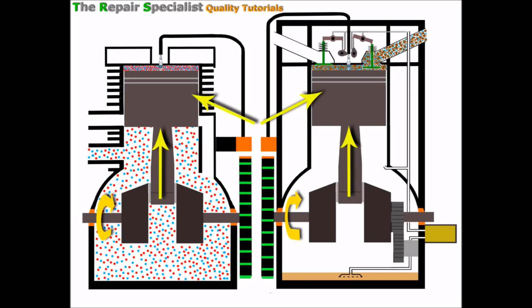Of course, now the pistons are in this position, those magnets on the flywheels are going to instantaneously pass the coil packs, generating and transferring the electrical energy, which again of course travels up each of the HT leads to the spark plugs. That again stimulates each spark plug to fire, and there's still a spark here on the four-stroke, even though we're at the end of the exhaust stroke, and there doesn't really need to be because it's not a power stroke. It still sparks because that magnet that passes the coil pack does so every 360 degrees, and that generates the spark.